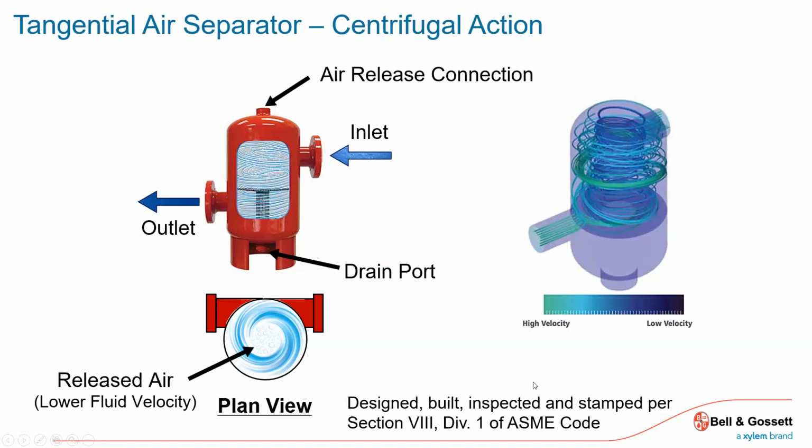So as it comes in, the heavier air-free water gets flung along the outside edge, and it creates this centrifugal force chasing after the outlet down here. So I'm coming in, heavier water flung around the outer edges, chasing after the suction of that pump. That's your low pressure. High pressure goes to low, it's going to the suction.